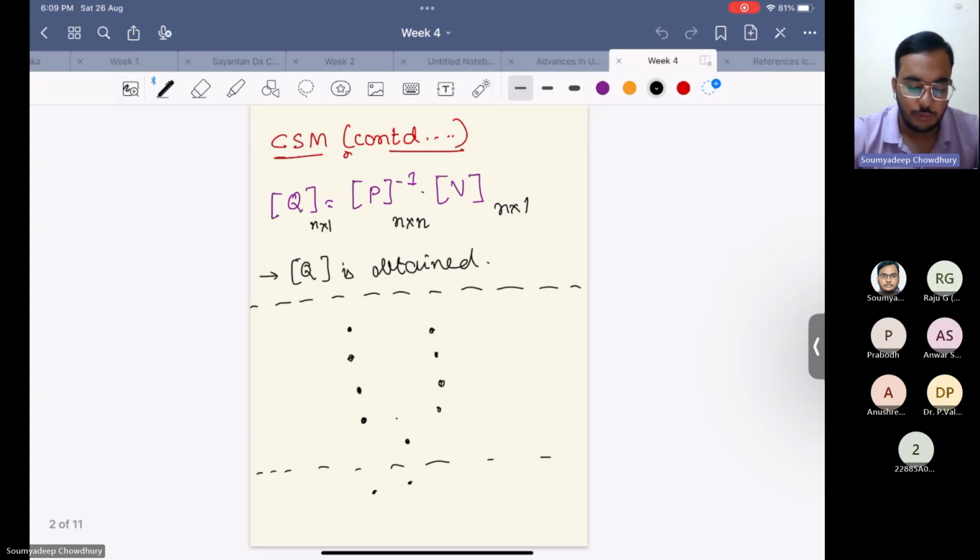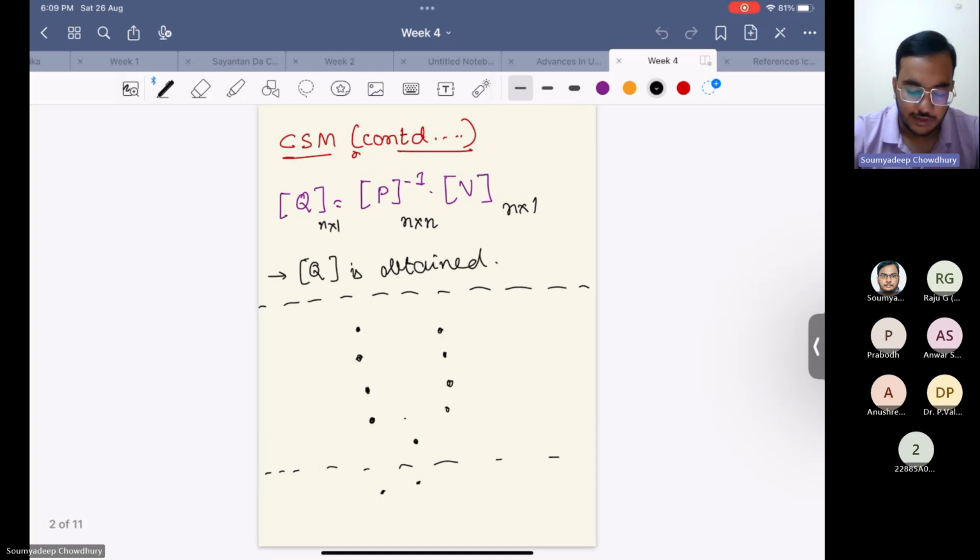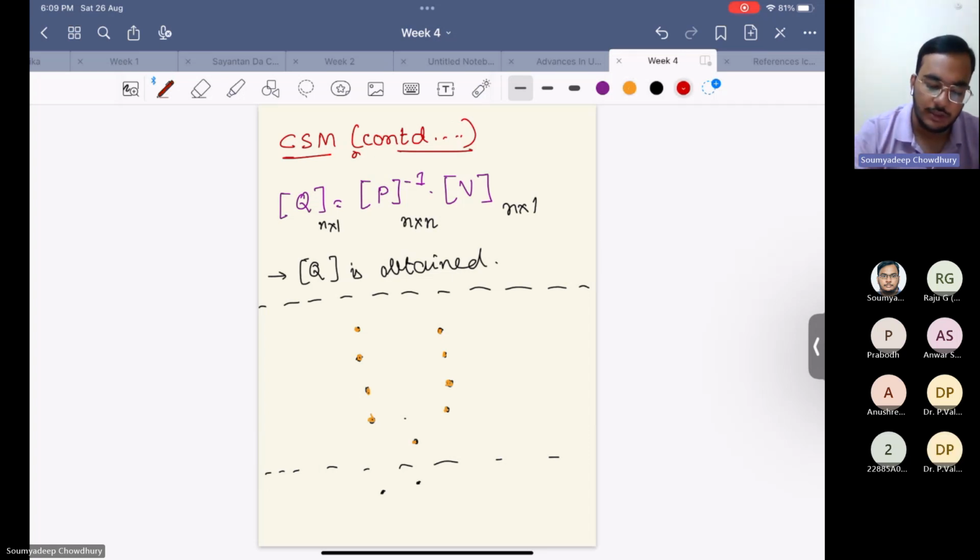So I had described using point charges. We had a rod plane type of electrode, and we had discretized that into multiple point charges, as you can see here. According to the geometry of the system, we have discretized it into different contour points, and for each contour point, we had one simulation charge.